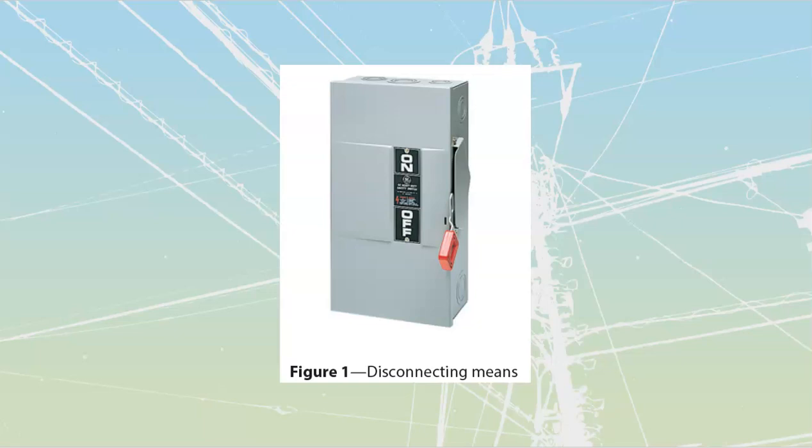You are never, ever authorized to go and work on a system live. There's huge amounts of paperwork that need to be done before you're even allowed to replace a breaker inside of a live panel or replace a switch or anything like that. You're supposed to have written work orders. It's supposed to be provable that it is absolutely impossible for that system to be shut down, etc.